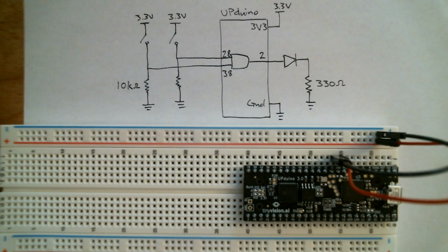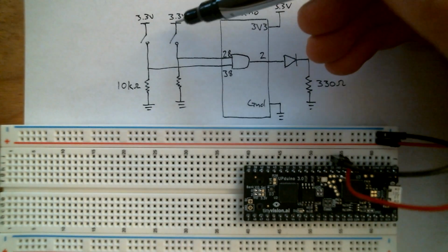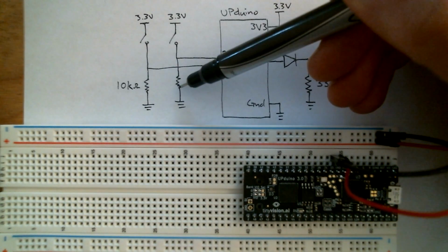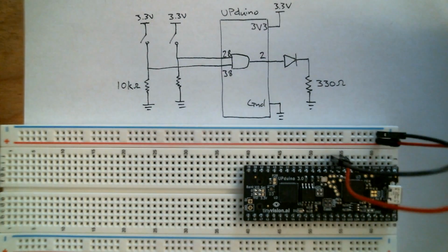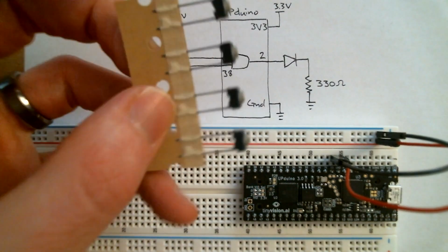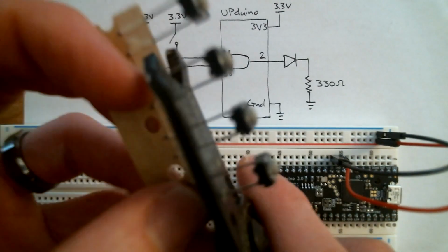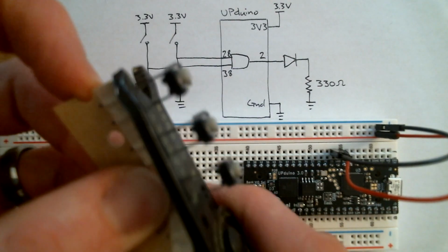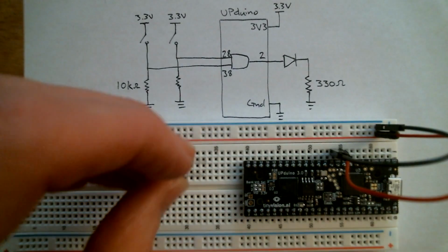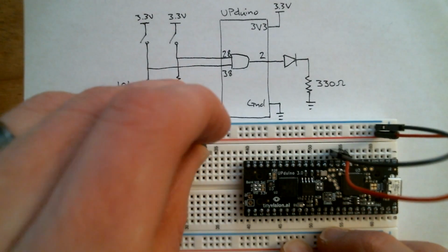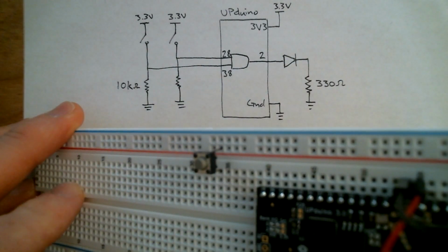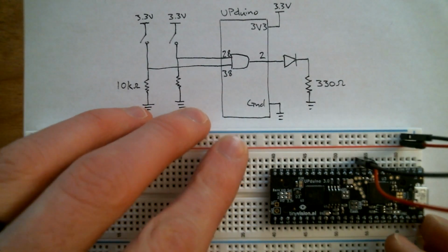Okay, the next thing we're going to want to do is we've got our switches. So they're going from 3.3 volts, and then they're going to connect through a resistor and then back to ground. And so let's grab a switch. If you've got your switches on one of these paper tapes, you'll just want to get a pair of wire cutters and clip them off. So you've got your switch like this, and now we can go ahead and plug it in. One way we could do it is just plug it directly into the 3.3 volt rail, like that, and then into a particular spot.